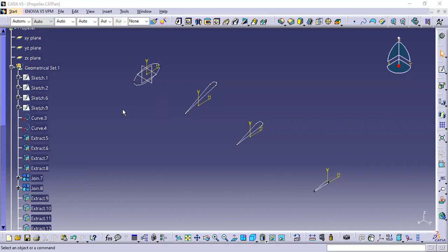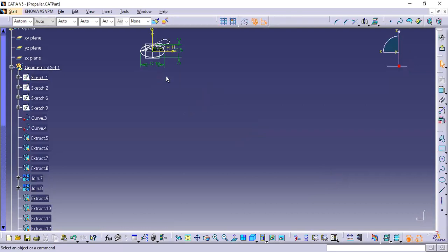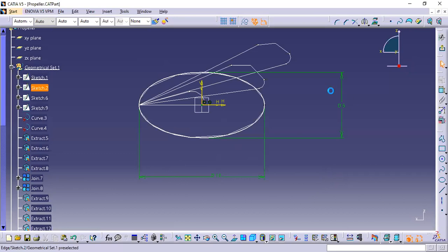This is Ayman Muhammad, and today I'm going to show you how I did the propeller for the quadcopter design. As we can see, first of all, we started with the center of the propeller. The propeller center consists of basically an ellipse shape with a height of 5 mm and the diameter of the ellipse of 10 mm as well.